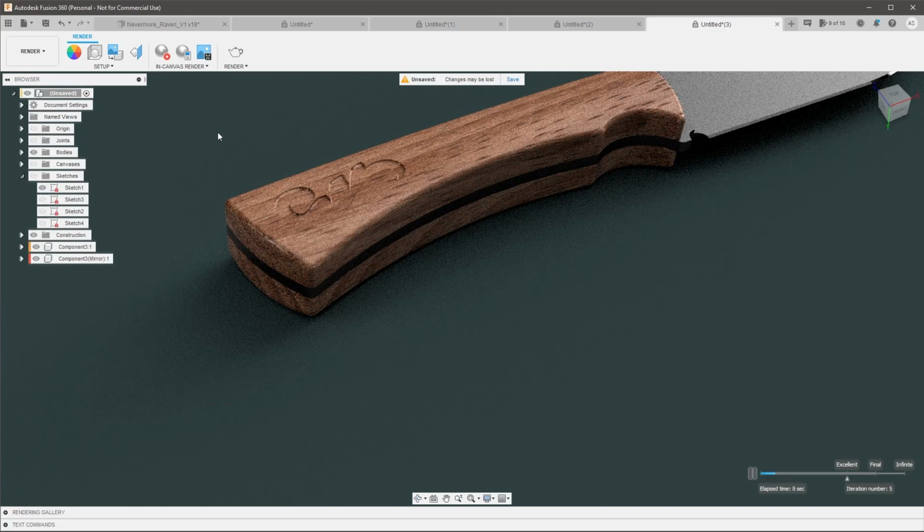versus the regular tools. Because when I use the regular tools, it's because I care about the dimensions of what I'm drawing. When I reach for the spline, that's usually when I'm dealing with geometry that I simply can't constrain with the regular tools, or it would take me an astronomical amount of time to do. And so for me, the benchmark is, is it worth my time to go through and constrain it? And if yes, then I will do it. And if it's not worth my time and I want to just capture the essence of whatever that shape is, then I will reach for a spline.